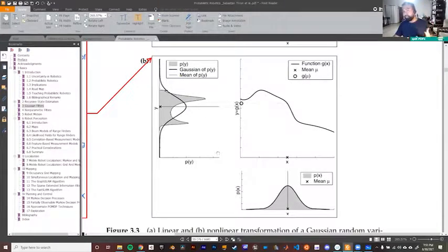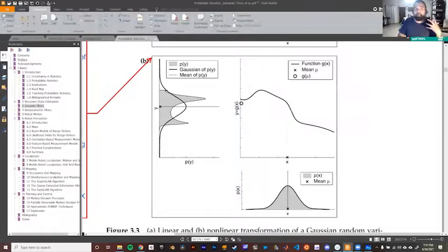So the EKF, the extended Kalman filter, solves this problem. What the extended Kalman filter does is, at this point where the mean is, it approximates a linear graph. The actual motion model is non-linear, but it makes an approximation of this curve around this point.